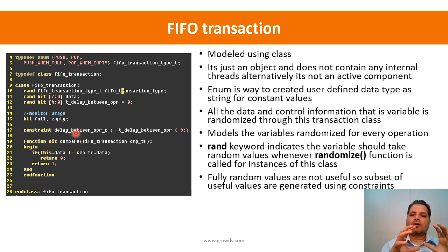Instead of those variables getting individually randomized as in Verilog, now they are collectively randomized at one place, and whatever relationship we require, we can define within this class. This class is now passed as a single entity, either through the interprocess communication mechanisms or as an argument to tasks and functions, to another component within the test bench.